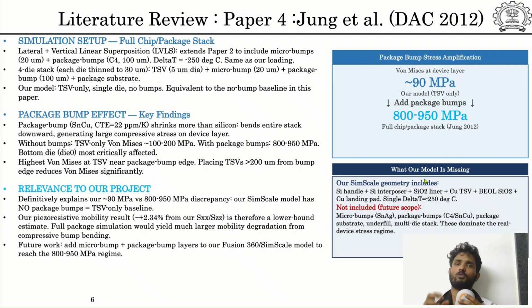Finally, relevance to our project. This explains why our result is lower than literature and shows that full package modeling is necessary for accurate stress prediction. Now in the last, I am going to compare and summarize the research papers. So overall, these studies show that both microstructure effects and package level effects are essential to accurately predict stress and reliability in TSV based systems.